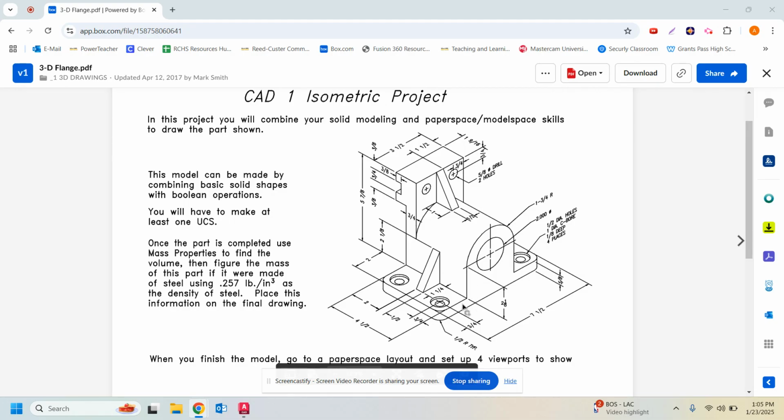on it. We've been talking likely about primitive shapes, and so if I look, this bottom piece, the support, is mainly made up of a rectangular prism or a box in AutoCAD, and then we've drilled holes in it here using the cylinder tool. I keep saying drill. It's really the subtract tool, the Boolean command in AutoCAD. We've got a wedge shape here, or a triangular prism. This is a cylinder hole. You can't see it in this drawing. It actually goes straight back through here.